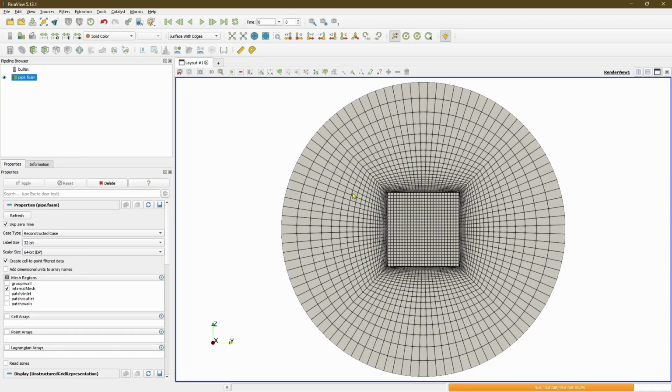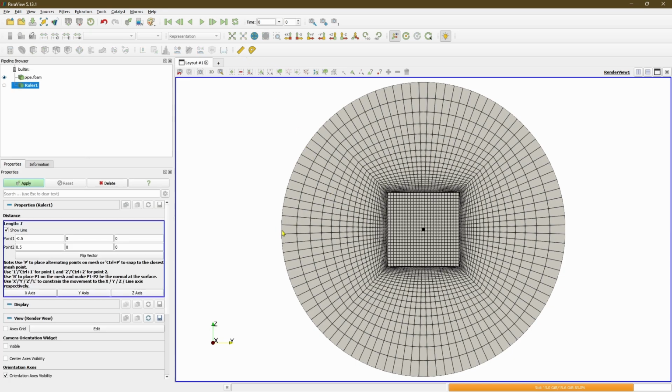Now, the fun part about the mesh that we have made right here with the Reynolds number 10,000, velocity 0.5 meters per second, and the diameter of 2 centimeters is that the first cell layer height is supposed to be somewhere around 1 mm. So if I want to take a look at that, you will see this is somewhere around 1 mm, and this is exactly why I cannot make more cell layers closer to my pipe right here.